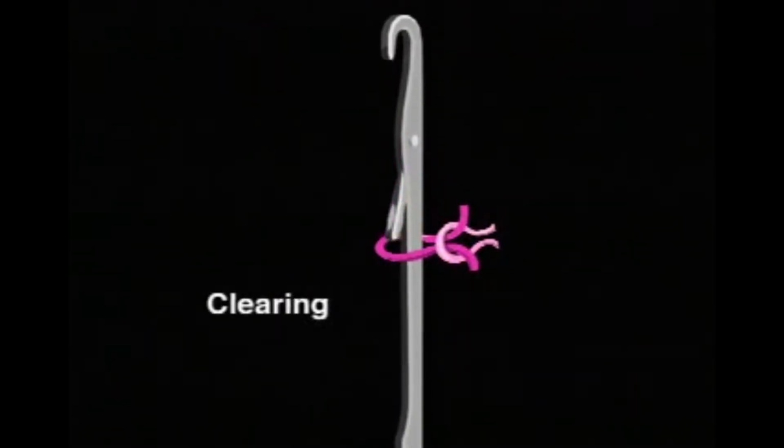At the bottom of the needle is a butt, which plays a part in controlling how needles activate, up or down. A needle with a latch is very efficient. When the latch needles are used to create weft knits, the knitting cycle can be completed without any auxiliary attachments. Here's how the latch needle works. At rest, or running position, a knit loop rests above or on the latch. As the needle moves up, the old loop, already formed, drops below and clears the latch.